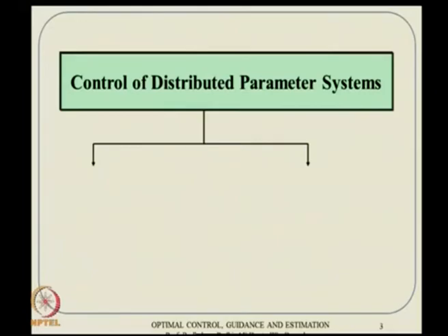And if you really want to approximate it through some sort of approximate lumped parameter system, through modal behavior, first mode, second mode, third mode, things like that, then also we need an infinite number of modes. So in that sense it is also an infinite dimensional system. That cannot be handled. So, there are ideas like design and then approximate. That means, you invoke infinite dimensional operator theory and do all sorts of algebra and math, and finally come up with an infinite dimensional controller basically.